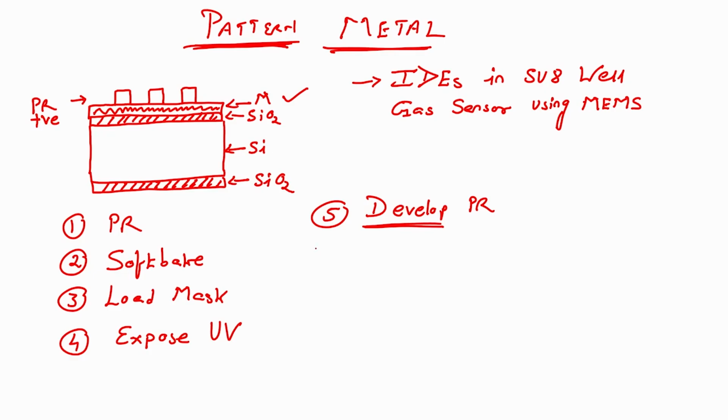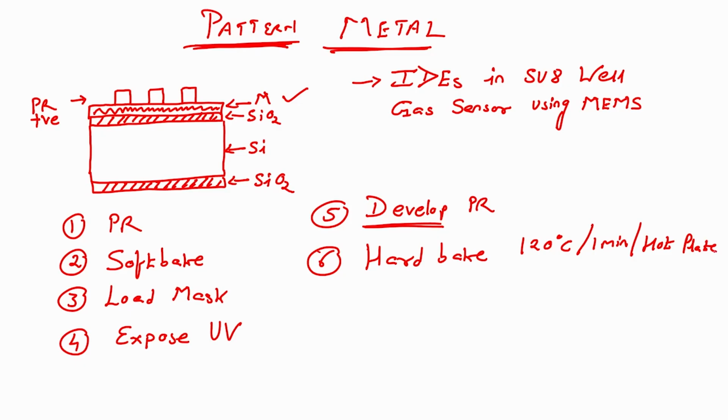So, next step would be, after developing, we will do hard bake. Hard bake is done at 120 degree, 1 minute, hot plate, correct, hard baking.